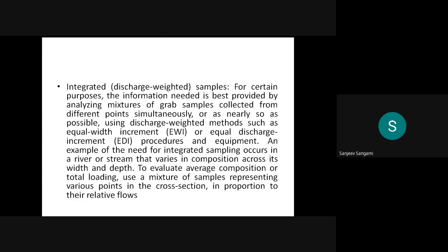Then integrated, that is, discharge weighted samples. For certain purposes, the information needed is best provided by analyzing mixtures of grab samples collected from different points simultaneously, or as nearly so as possible, using discharge weighted methods such as equal width increment or equal discharge increment procedures and equipment.